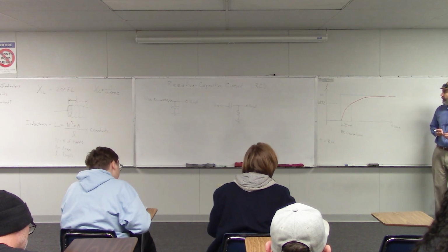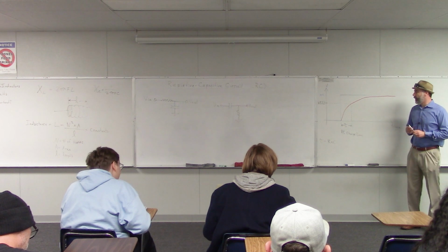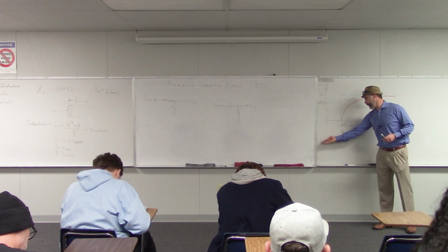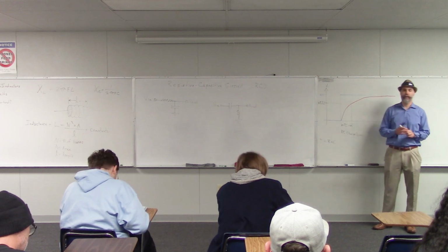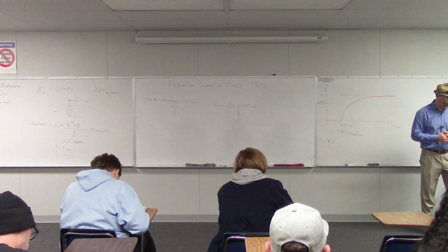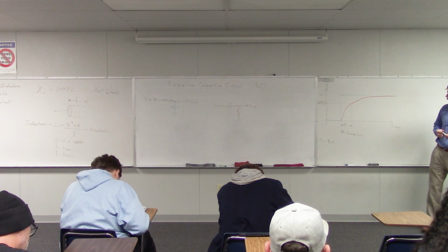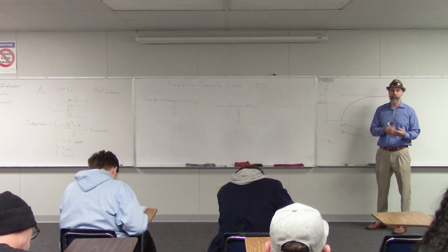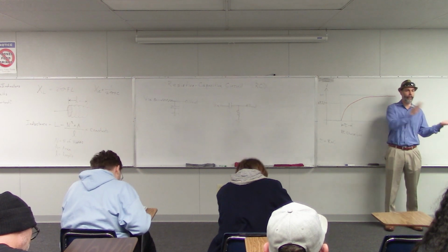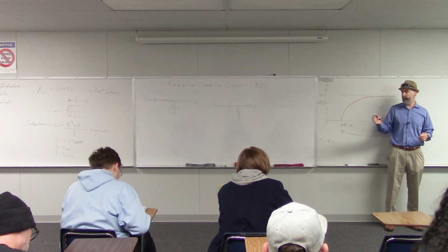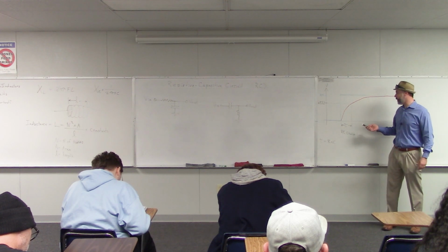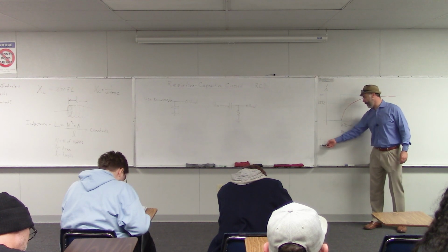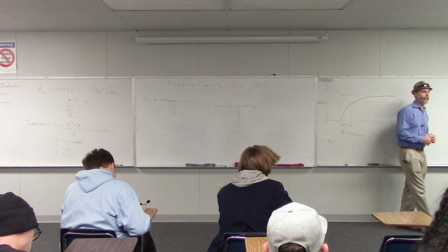Okay, so if you know your resistor and your capacitor, you can use them to calculate what that charge time will be. Equivalently, if you know what you want that charge time to be, say you want your blinker to stay on for 1 second and then go off for 1 second, and back and forth like that, you can use that time to find values of R and C that'll give you that time that you're looking for. Okay?